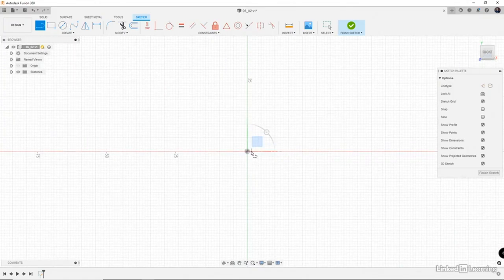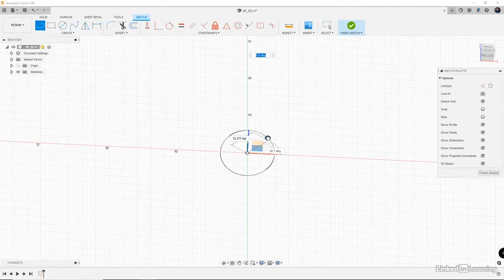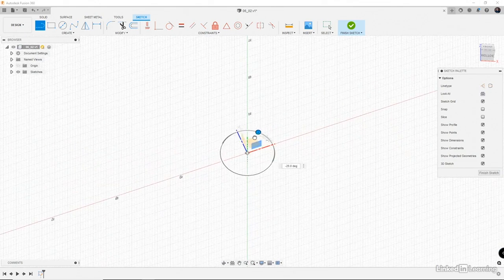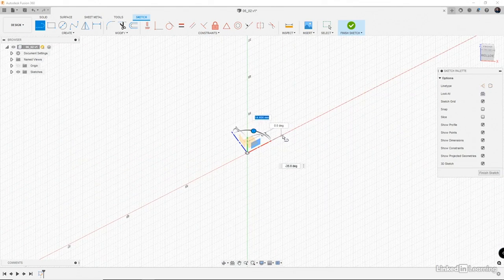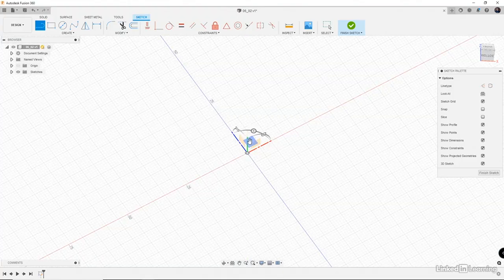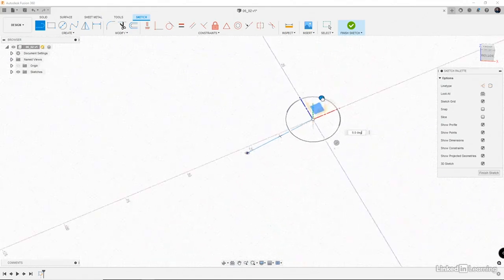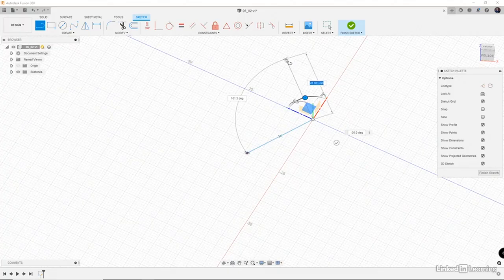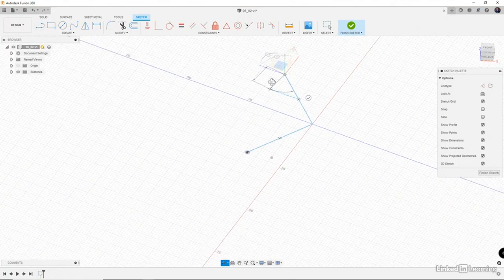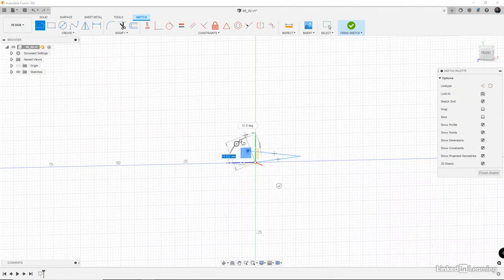So once we get into our start point here that we want, we can then move around and we can move any of these axes that we want. And then once we move the axis, we can reference to that new origin, or we can create any sort of geometry within this plane. Now we can also switch planes. So you can go to any plane that you want. Once you're done with your line, you want to click it right here, you can then edit this triad anywhere you want within this plane. So, you can build geometry as complicated as you want, and then you can build these very organic, complex shapes.